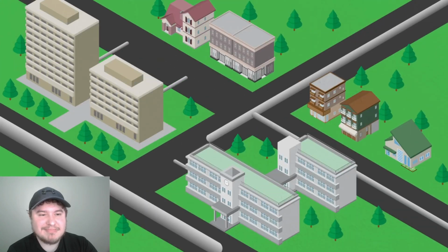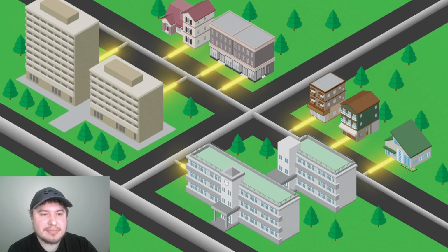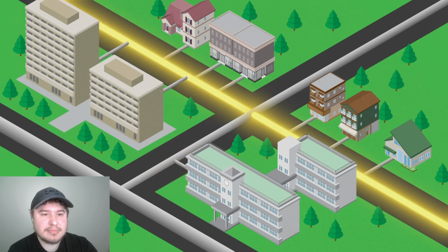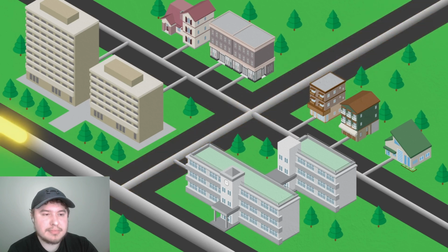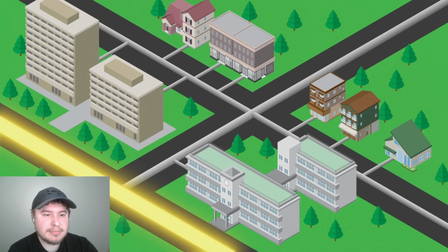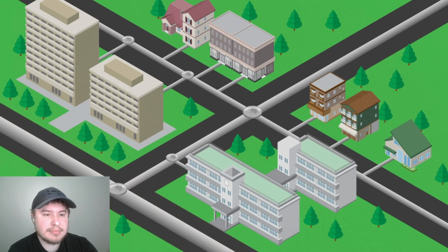Sewer networks have a tributary structure. Gravity carries waste along downward sloping pipes that converge and concentrate into larger and larger lines, like a big underground river system, but grosser. Terminology varies place to place, but in general it goes like this. Pipes that service individual buildings are usually called laterals, and those servicing particular streets are branches. Larger pipes that collect wastewater from multiple branches are called mains or trunk sewers, and the most significant lines furthest downstream in the system are usually called interceptors. And connecting each one is a manhole.